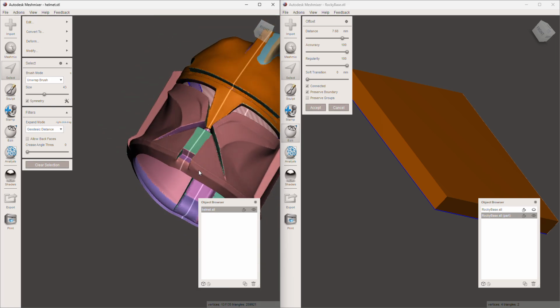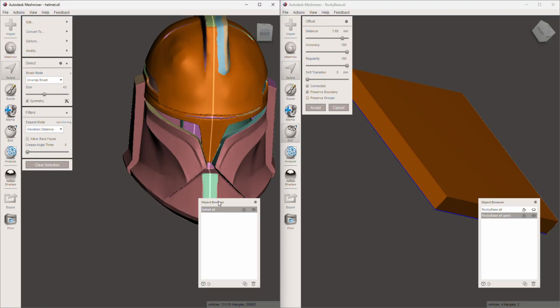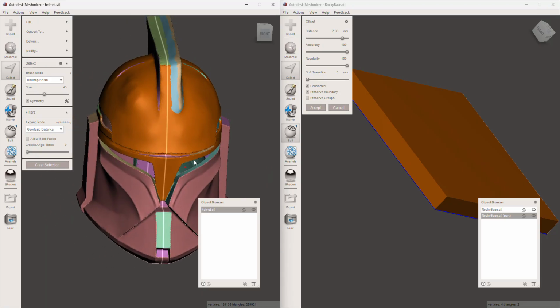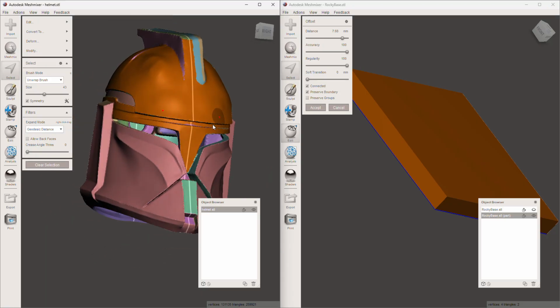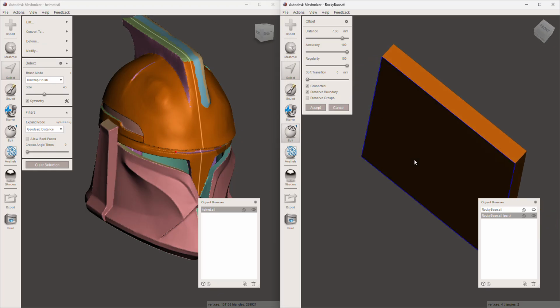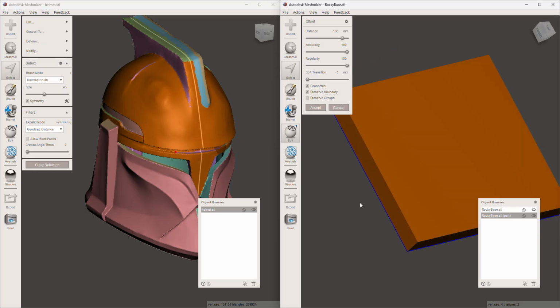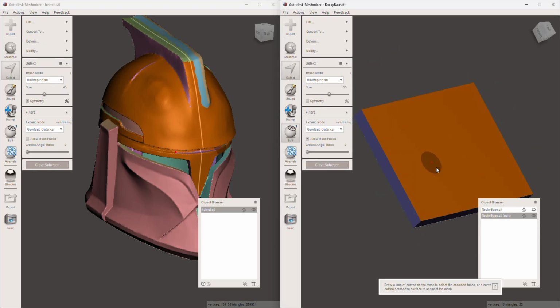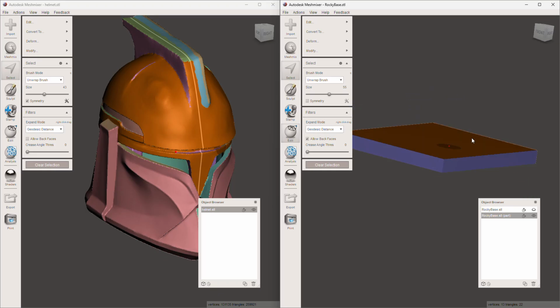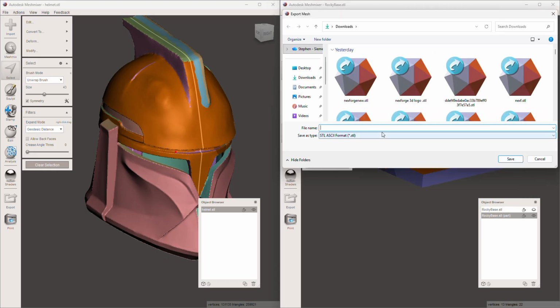And then again, just be patient with it. If it crashes, which it can do if it gets really detailed, just restart it and it'll work. But that's a critical tool as well. Okay. And then exporting, real quick, we'll say accept here. If I wanted, let's say this is something I liked and I wanted to export it, literally just go to export. I export all my stuff as STLs because I do 3D printing. Okay. So that's the long and short of it.